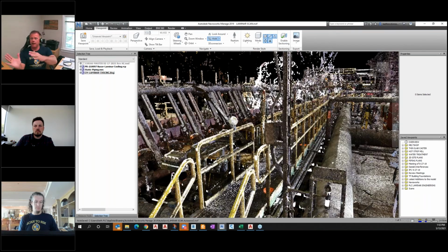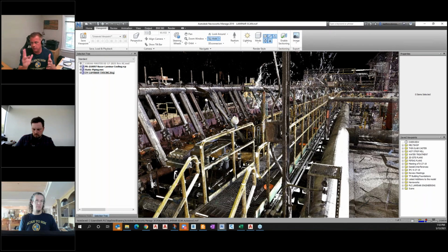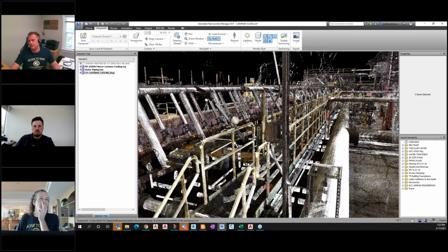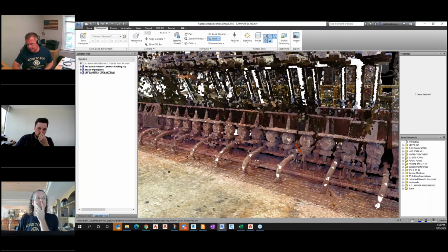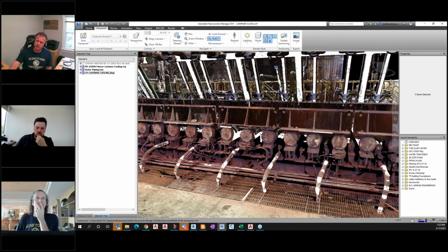So yeah, we're going to be taking all this equipment out here, and then we're going to be redesigning the catwalks. Two piping headers are going in here, a 44-inch and a 28-inch. So this is going to look completely different. But that's why we took the time to scan this, although we didn't get really good data on the steel that's there existing. But I will be using the extraction tool in Edgewise to extract that steel right below here. That's going to stay.